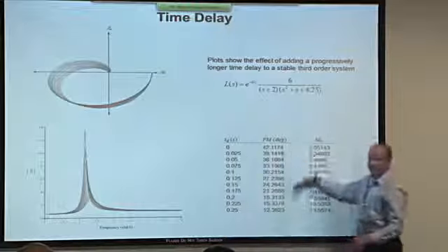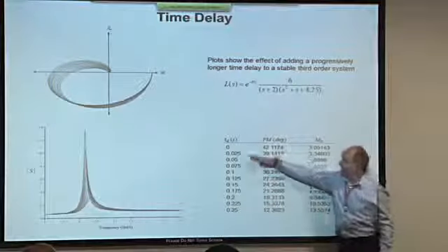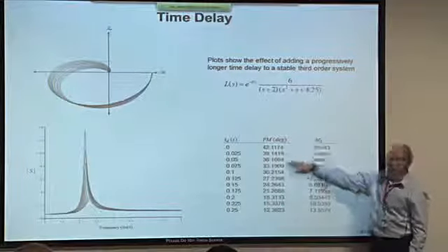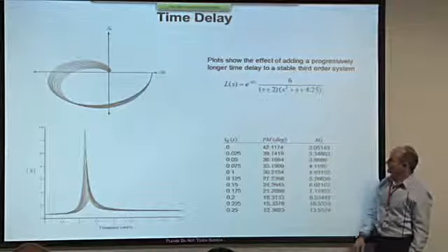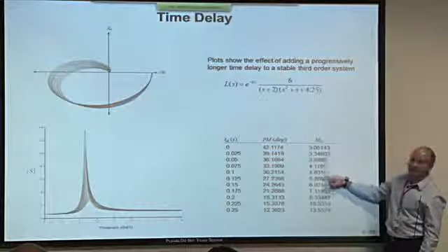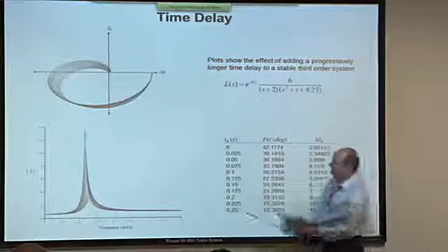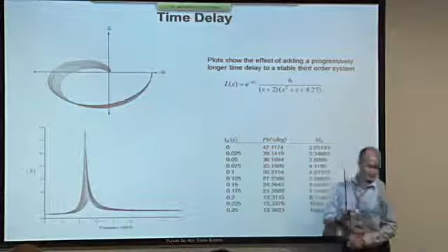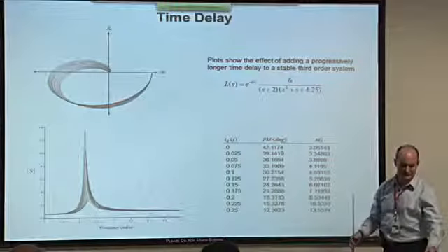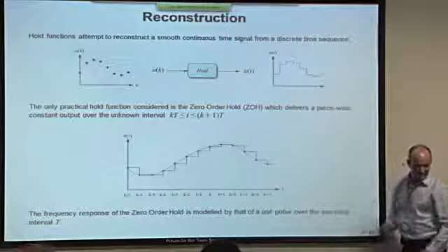So what I've got here is visual confirmation that time delay is eroding phase margin because there's frequency-dependent phase lag involved, and we're getting some very big numbers in the Ms. There's a sensitivity magnitude up here. I'm just saying take it seriously, that's all I'm saying.